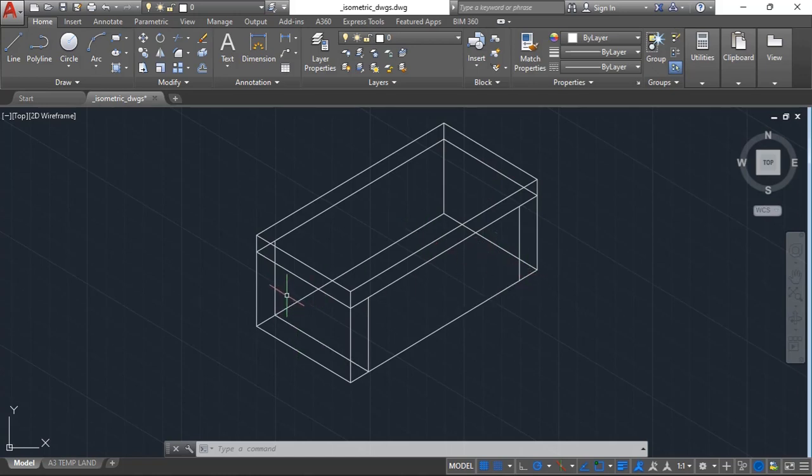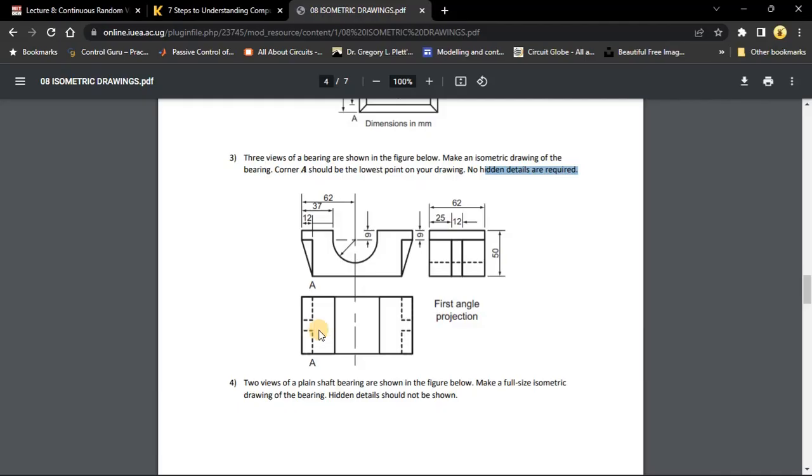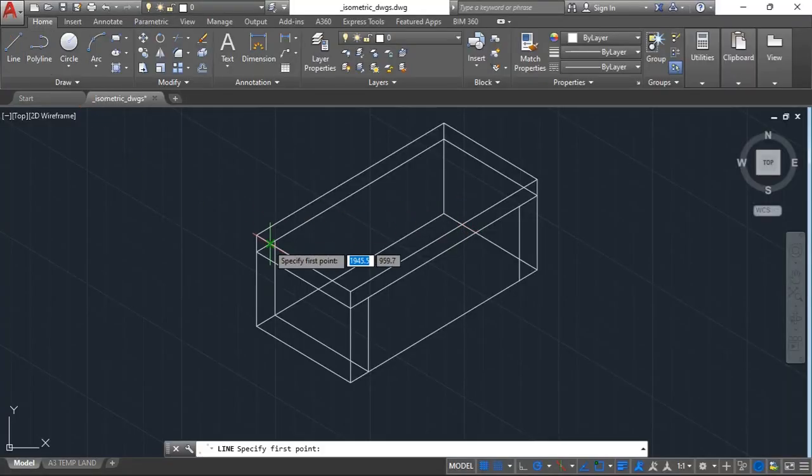And now what I'm going to do is to add that there's some slanting face here, at a distance of 25 from either end. Then it's 12 millimeters in thickness, so that's what I'm going to draw. So from here, from this, I'm tracking 2 points at the same time, which is not what I want to do. So 25,